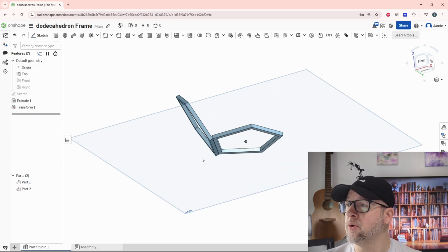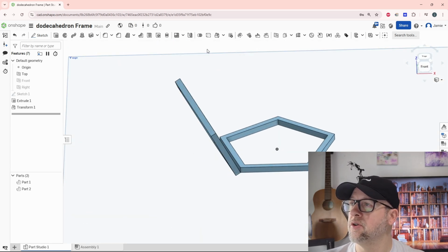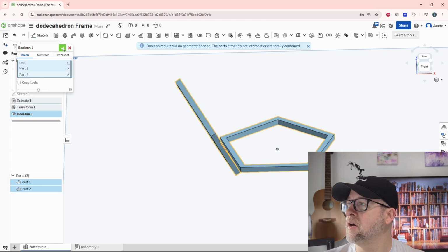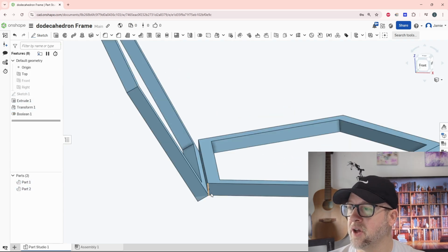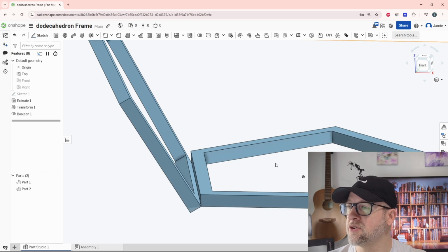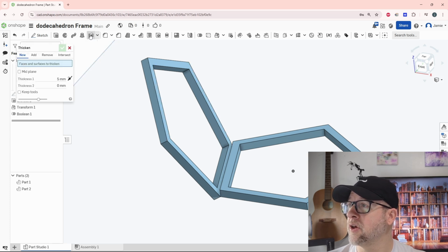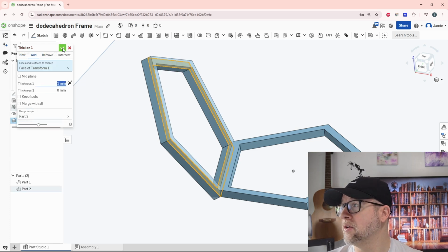Okay, and so now we got a copied part, and let's do a test real quick. I want to see if this unites together. Let's see, this guy to this guy, is it going to unite? It does not unite, so it's not touching, so we need to make this touch. So I think what we'll do is we'll make this a little bit thicker. We're going to add 1 millimeter thickness to this. So thicken. We're going to click on this guy right here. We're going to click on 1 millimeter. Okay, and then we're going to say okay.